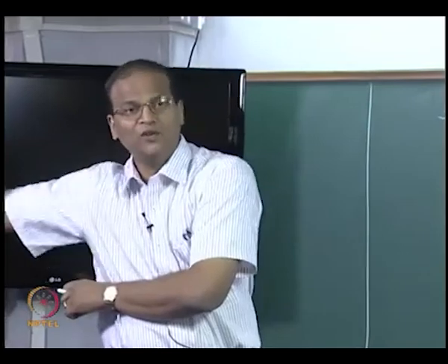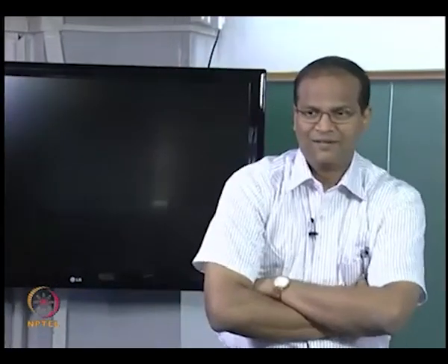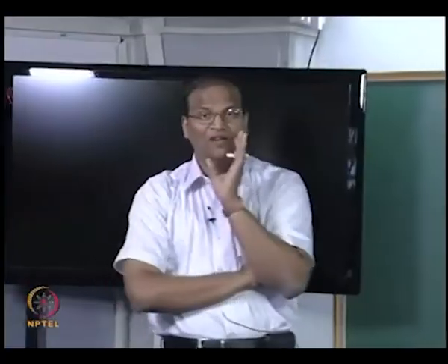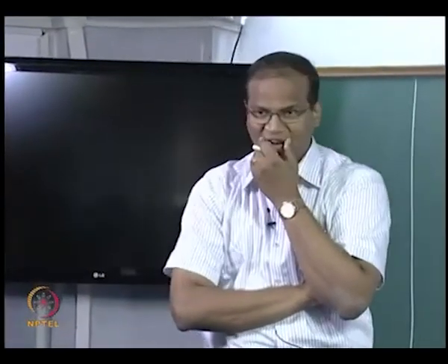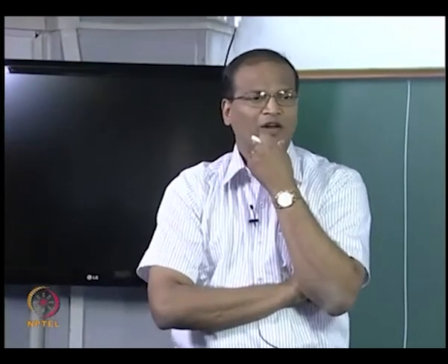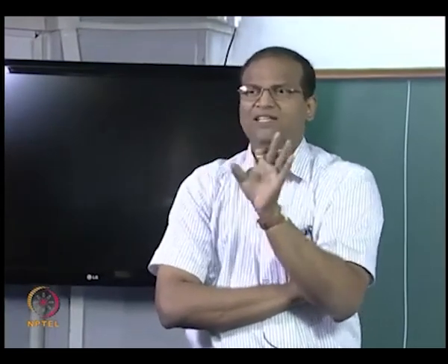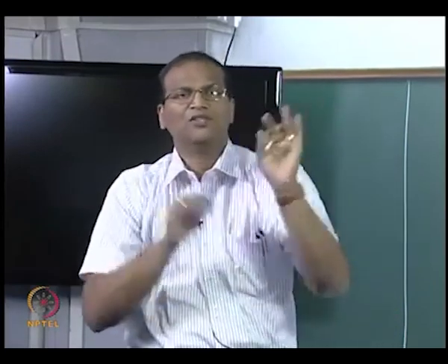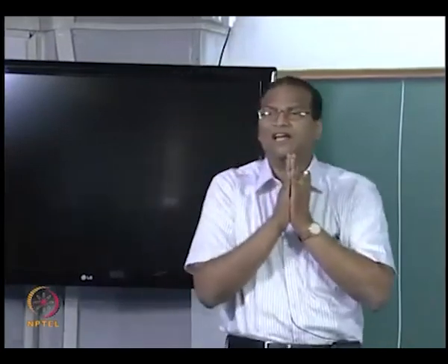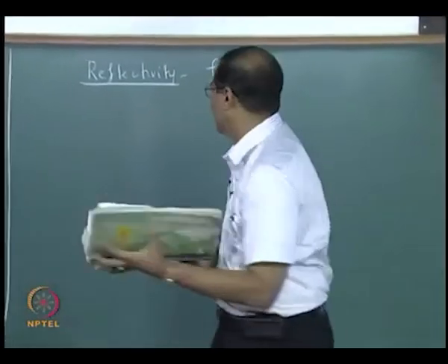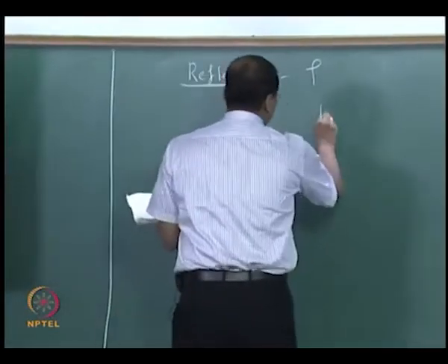To all this you add the spectral dependence. Okay. So reflectivity is a very dangerous property. If you really want to get to the bottom of it, it is going to take a long time. So I will just define the basic bidirectional reflectivity, and then we will proceed to those reflectivities which are of engineering significance. But reflectivity is a highly involved property. So let us draw a picture and then things will become clear. Let us take the spherical coordinate system.